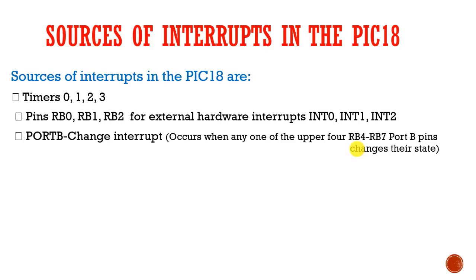So these things we'll discuss in the coming section, but keep this in your mind: whatever module has a flag is able to generate interrupts in PIC18F452. You can see that timers have flags. For external interrupts you have never seen a flag, because this is an external hardware interrupt, INT0, INT1 and INT2.